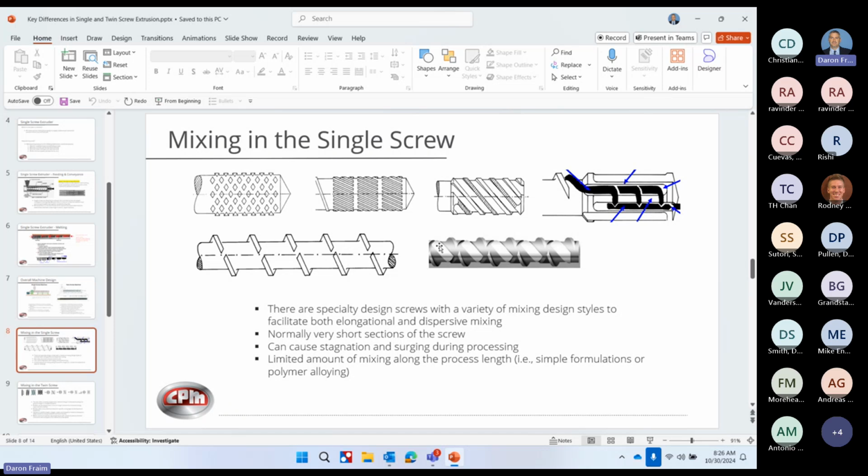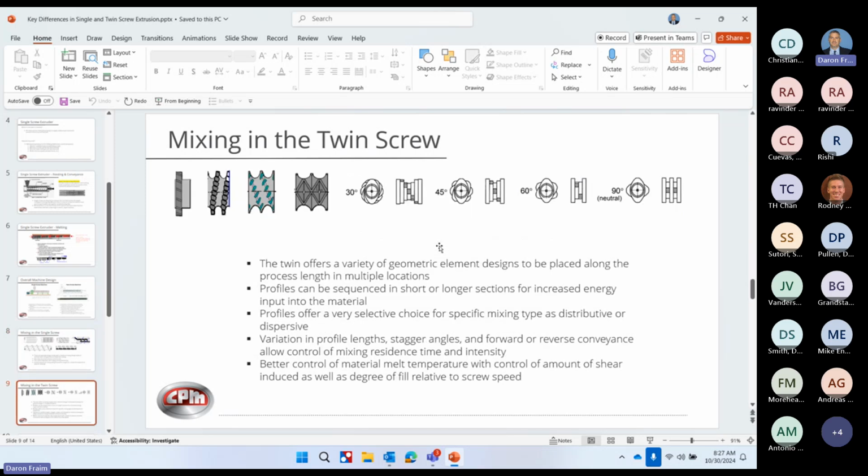I have used a single screw where we incorporated a PE wax as an internal lubricant mixed in with a polymer. You will also see a single screw where you disperse color. Of course, like injection molding machines, if they're going to add color to their finished part, they'll bring the parent polymer in and then they'll dose in their color masterbatch pellet, usually in the 2 to 4% range. So they do have some mixing, but it's extremely limited. You know, 2-component type systems. Again, we touched on it.